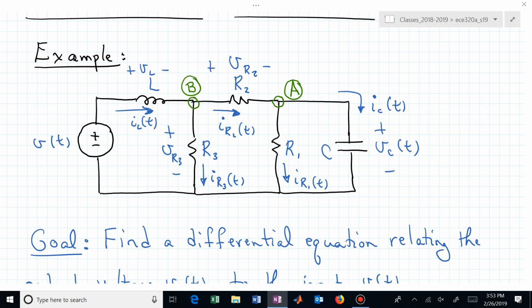It's going to depend on the R, L, and C's, right? But naturally, what's going to happen? You've got resistors. What are they doing? They're removing energy from that circuit. So you would expect, if this is even complex roots, maybe they'll shake a little bit with some sinusoidal behavior, but they're going to exponentially collapse.